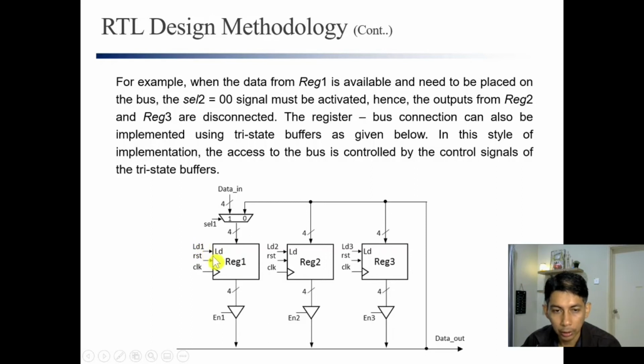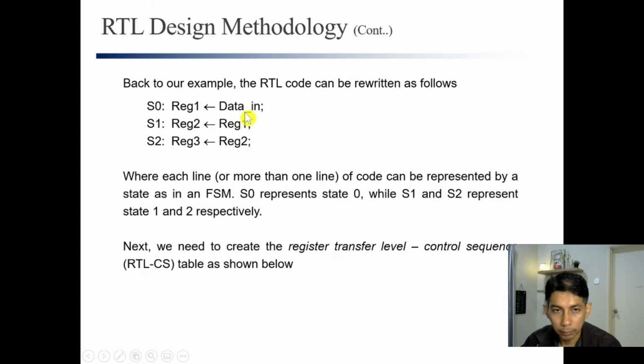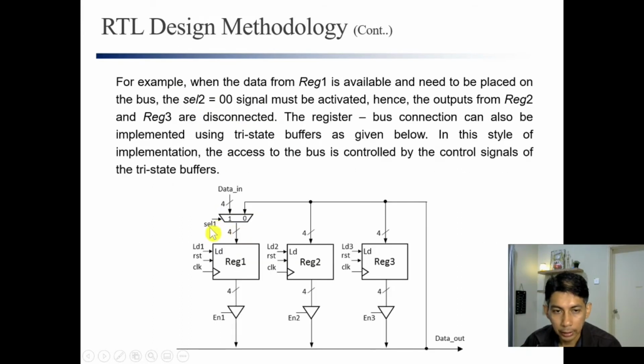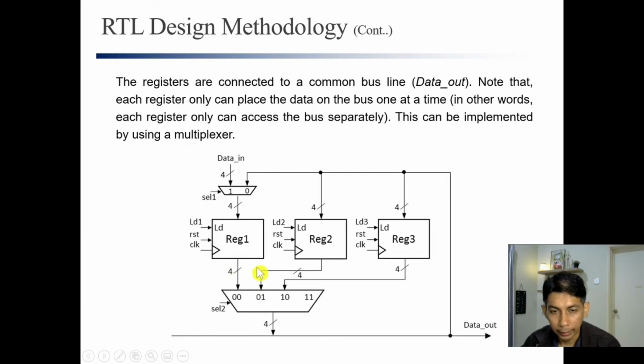This is load. If you do not activate this LD, the data cannot go into this register. This means that to do this, you need to set SEL1 to 1 and set LD1 to 1. And the other signals are don't care actually.